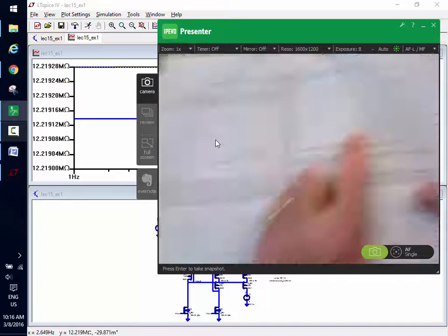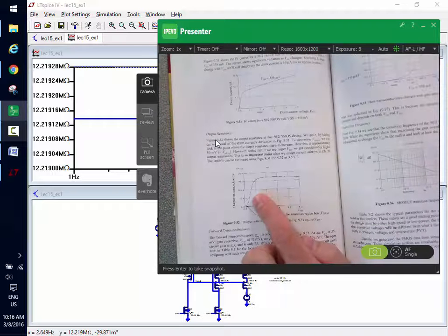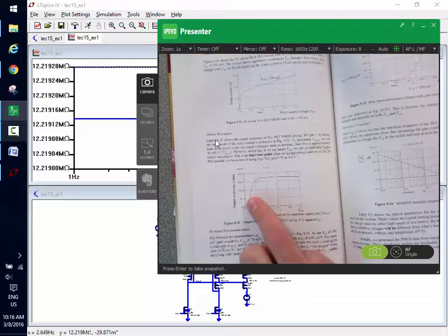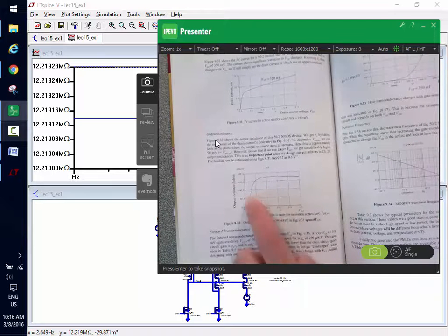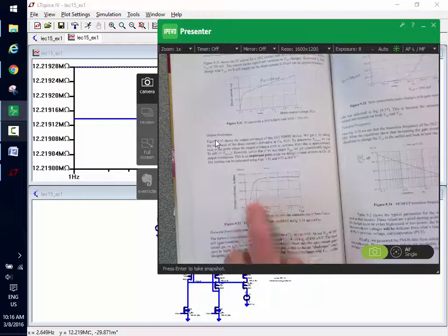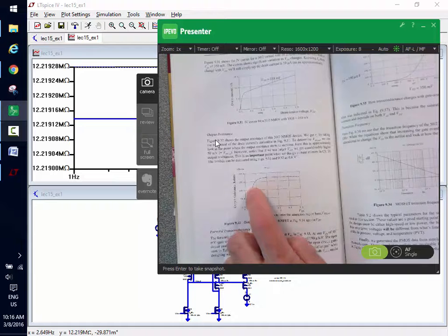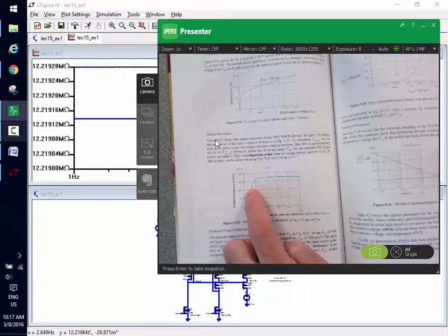And we said, wow, where is it? Wow, look at this. If the voltage across the device changes a little bit, the output resistance can change by an order of magnitude or more, a factor of 10. So when I get variations in the output resistance, I know it's going to be related to the drain to source voltage. I know what you're thinking. He's only gone over that 3 times before, and he expects me to remember it. What's wrong with him? Just joking.